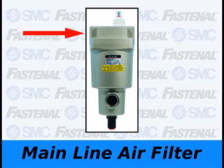Air comes in here and it passes through the filter element to trap dust and dirt. Any condensation the dryer didn't catch will accumulate in the bowl. An optional automatic drain empties the bowl even if the user forgets to. An optional element checker pops up red when it's time to change out the filter element inside.